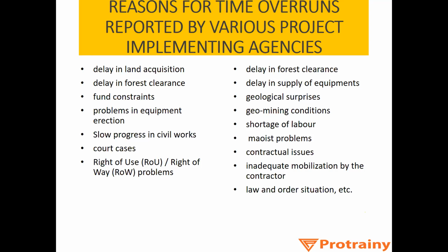There will be various paperwork, various formalities. The supplier has already told you that once I receive your purchase order, it will require 3.5 to 4 months to deliver all the materials at your site. So we, as planners, should understand that we should consider at least 14, 15 or 20 days as a buffer period, and we should order that material 4.5 to 5 months before we actually require it at site.